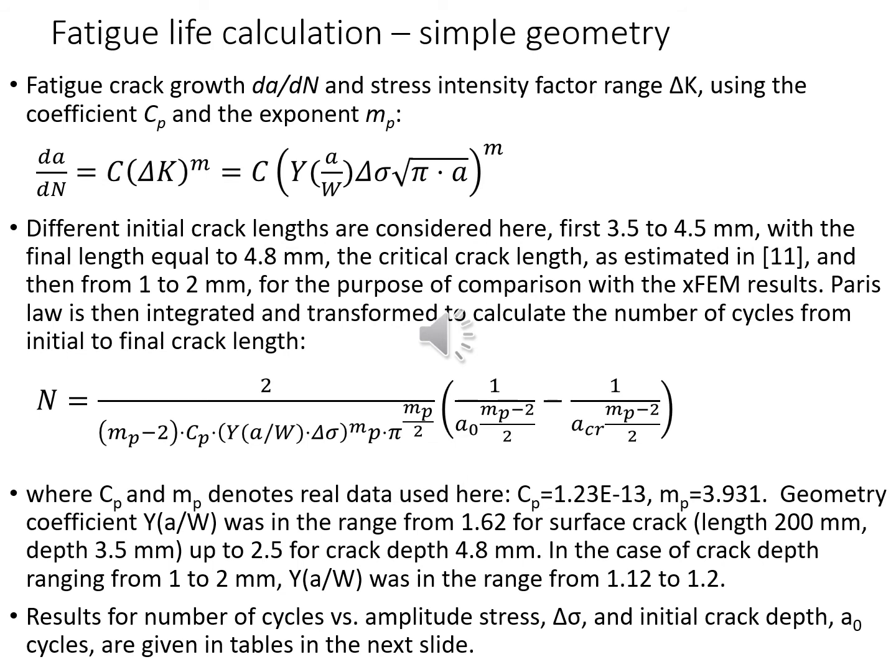Now, fatigue life calculation was done in two ways. Since this is simple geometry, the first way was analytical, direct integration of Paris law. The second was the finite element method. It will be shown later. As for the Paris law, it's given here in the usual exponential form. Fatigue crack rate depends on two material parameters, C and m, and delta K is an important parameter as well.